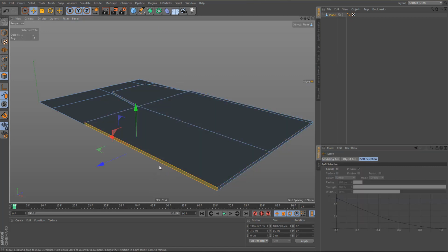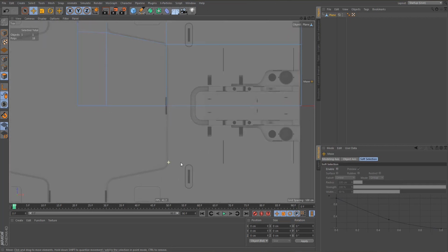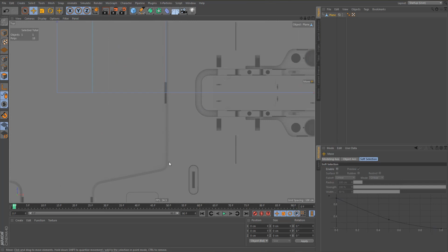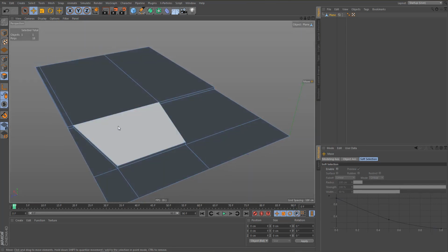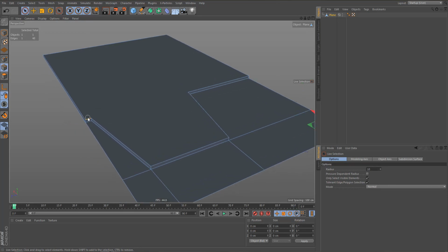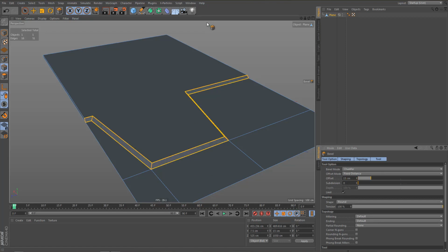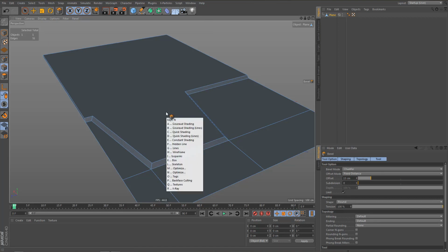And let's get rid of that polygon at the center. And you can see in the reference image that we also have this bevel here. So I'm going to add that, but before I do, I'm going to dissolve these edges in order to make the bevel work properly. So let's select these edges, and I will bevel these using limit, and I'll use the same offset that I used for extruding, which is 15. Let's deselect everything and optimize the object.